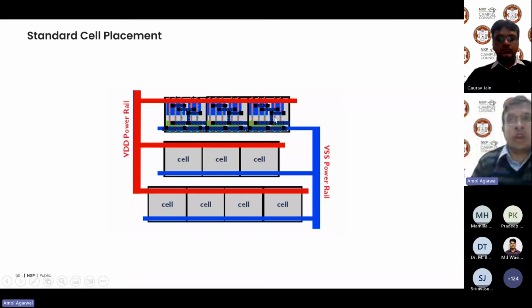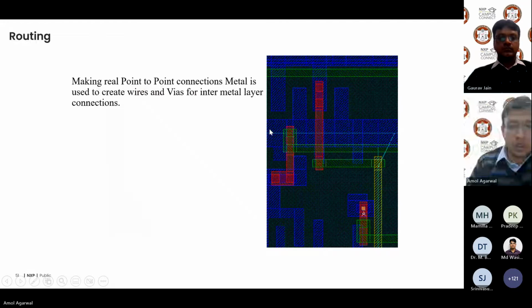These standard cells come as part of a package for you. I mean, you are not developing these standard cells. These AND gates or OR gates are coming from a library vendor. It could be a library coming from TSMC, or you could develop an in-house library also. But it's not that you are developing this library on your own for a chip. This is coming as a pre-hardened library gate. But yes, compared to memory, it would be smaller in shape, and you would place it between the rails.